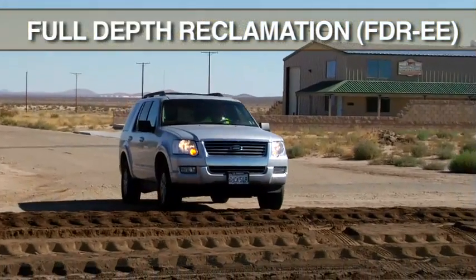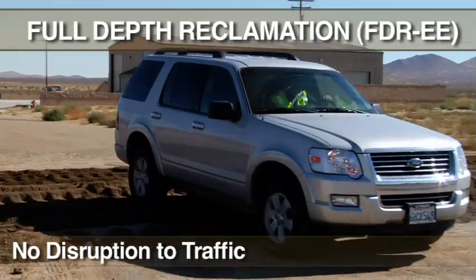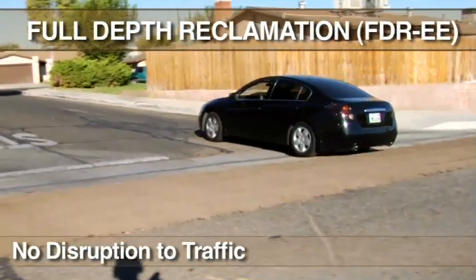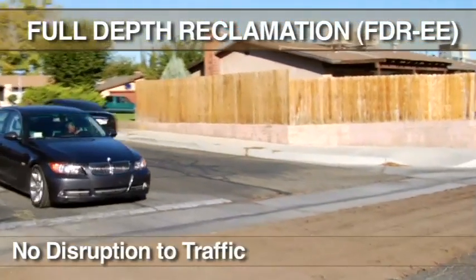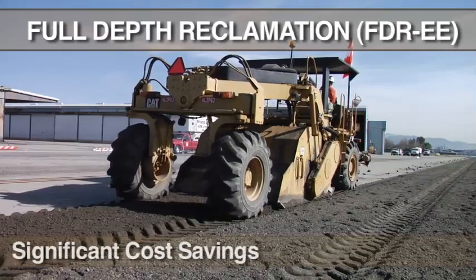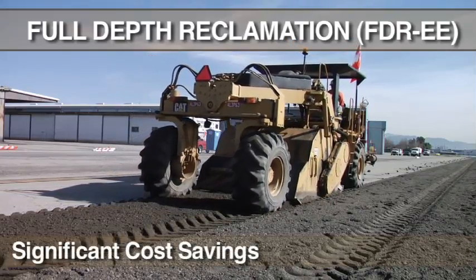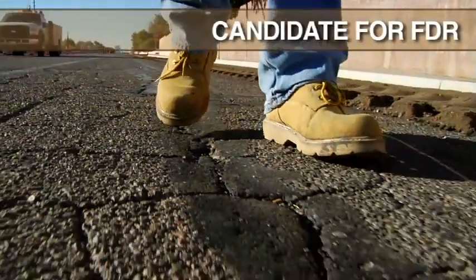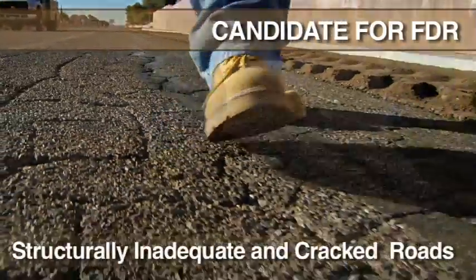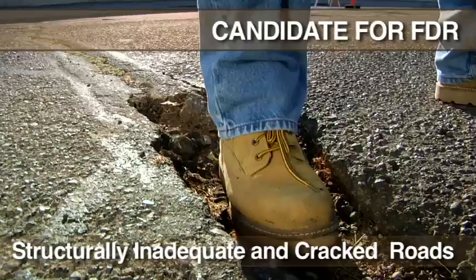The traveling public suffers little disruption since the pulverized material remains in place and does not create a long-term lane closure. The stabilized materials can then be opened to cross-traffic in less than 1 hour versus days with typical reconstruction. Significant savings of 30 to 40% have been realized by many agencies when compared to traditional reconstruction cost. With this in mind, an ideal candidate for FDR are roads that are structurally inadequate and are suffering from cracks, potholes, and loss of bonding between pavement layers.